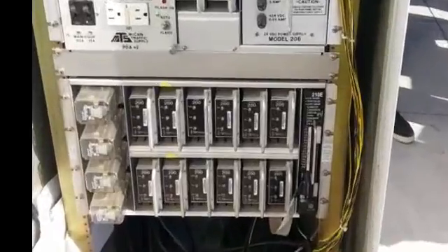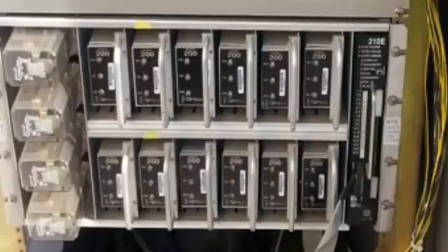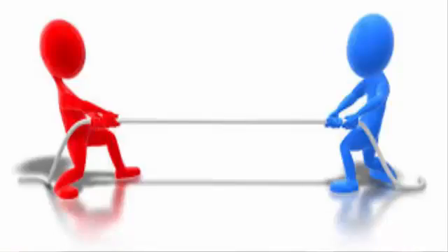settings. The conflict monitor, also known as the malfunction management unit, checks the operation of the traffic signal controller to make sure that an electrical glitch does not create a dangerous situation on the intersection. It has 3 basic functions. Number 1, to check for simultaneous activation of conflicting phases.